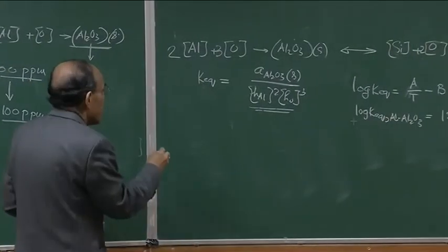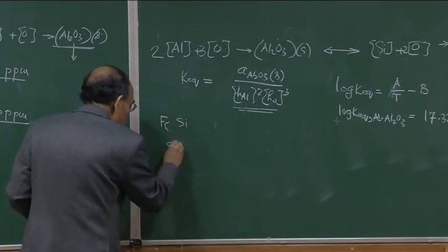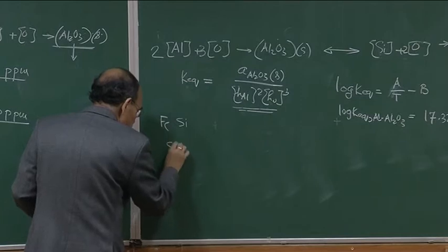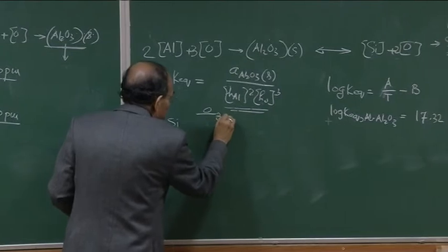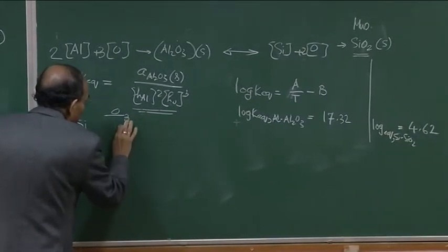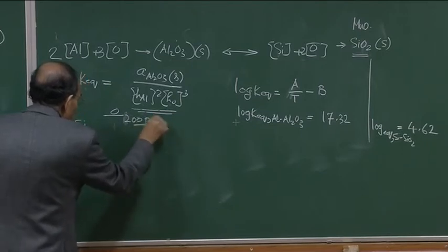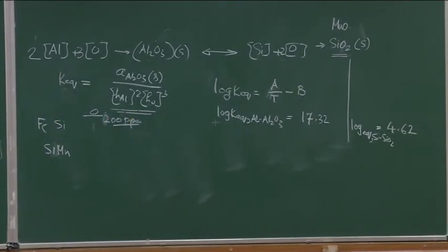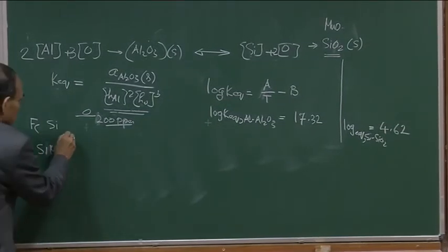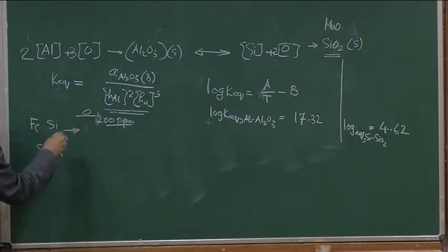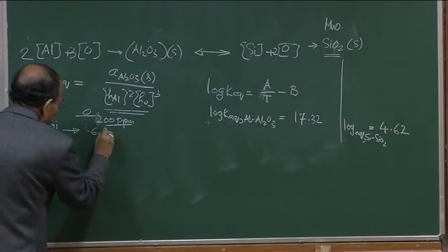That is why I say, if I use ferrosilicon alone as opposed to silico-manganese, and my target oxygen in both cases is suppose 200 ppm, then it is possible that the silicon content of the bath in this particular case is suppose 0.6 wt%.